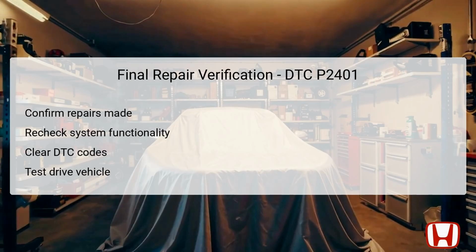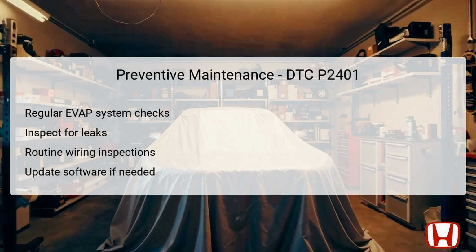It's crucial to clear any diagnostic trouble codes, DTCs, stored in the PCM to reset the system, followed by a comprehensive test drive of the vehicle. During the drive, the technician should observe for any repeat activation of the check engine light and verify that all system parameters are within expected ranges. This final verification step serves as a crucial checkpoint to ensure that the repair work is effective and eliminates further issues from arising. Preventive maintenance is vital to ensure that issues related to DTC P2401 do not recur.